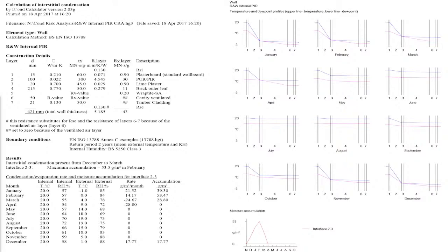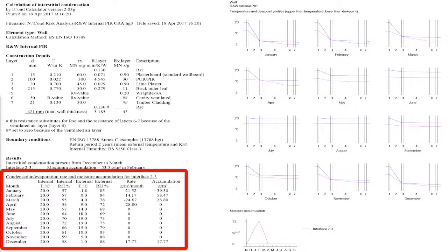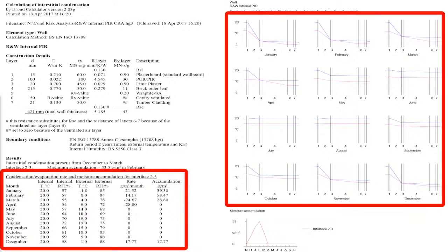Developed back in 1958 for use in lightweight buildings, the simplified calculation used by the Glaser method is based on average monthly temperatures, vapour pressure, and steady-state conduction of heat to determine if critical condensation points are reached within 1 year. The limitation of this approach is that Glaser assumes vapour moves only one way, from inside to outside.